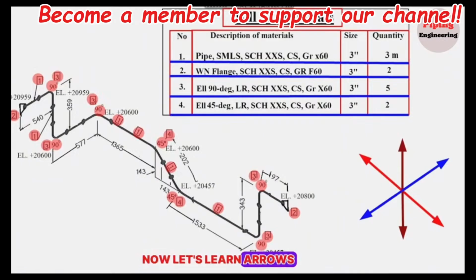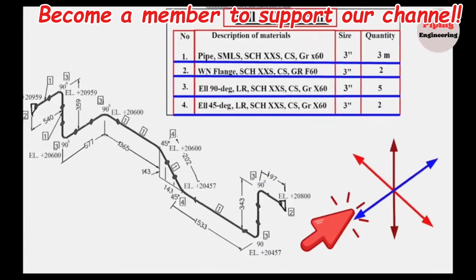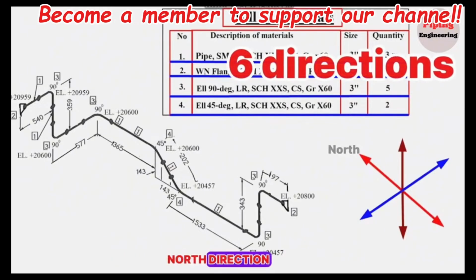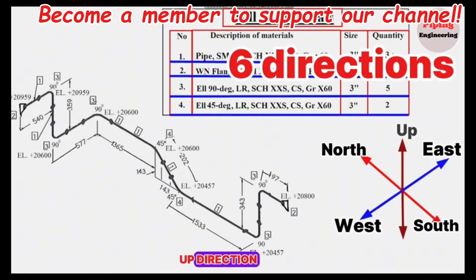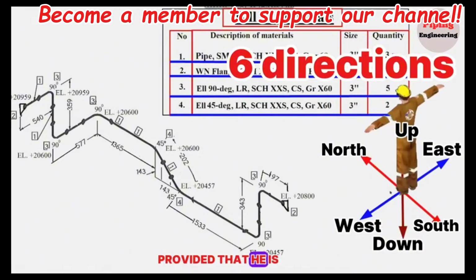Now, let's learn the arrows showing the directions in the piping isometric drawing. Piping engineers must know these arrows well while reading piping drawings. There are 6 directions in piping isometric drawings: north direction, south direction, east direction, west direction, up direction, down direction. The person reading the drawing should imagine himself facing north, provided that he is in the center of these directions. We will start to read this pipe drawing from this point.